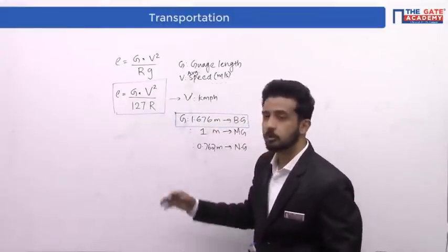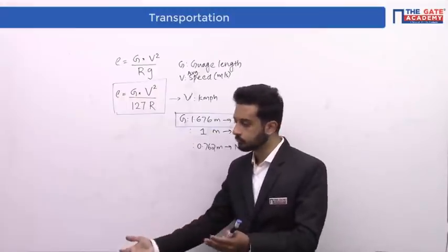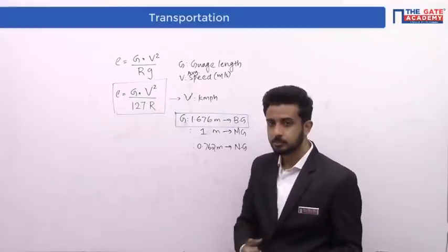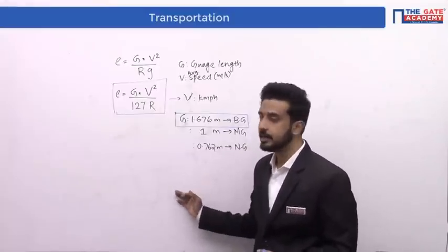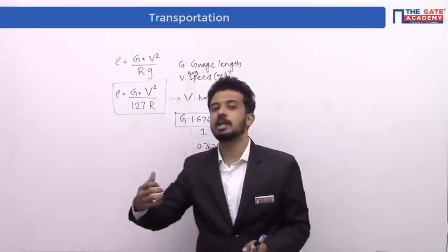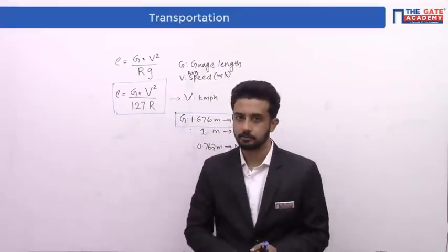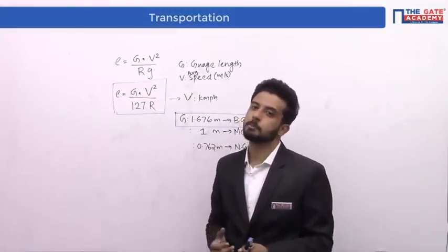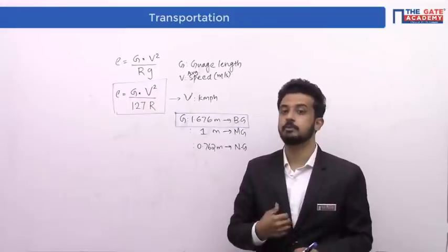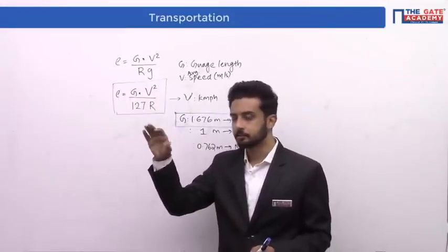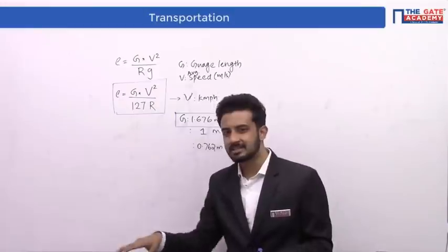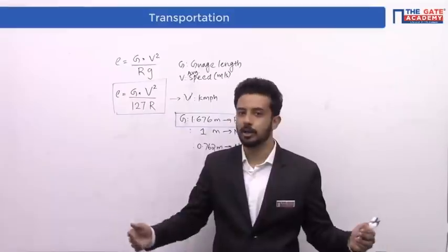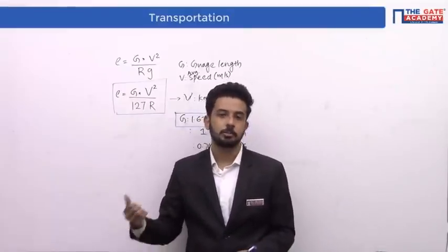But whenever we are providing the super elevation, whenever we are raising the outer edge of the rail with respect to the inner edge, regarding the average speed only we will decide what should be that height. We will not be providing for the maximum speed. We will be providing for average speed only, which means for some trains it is giving less than what is required, and for some other trains they are getting enough super elevation.